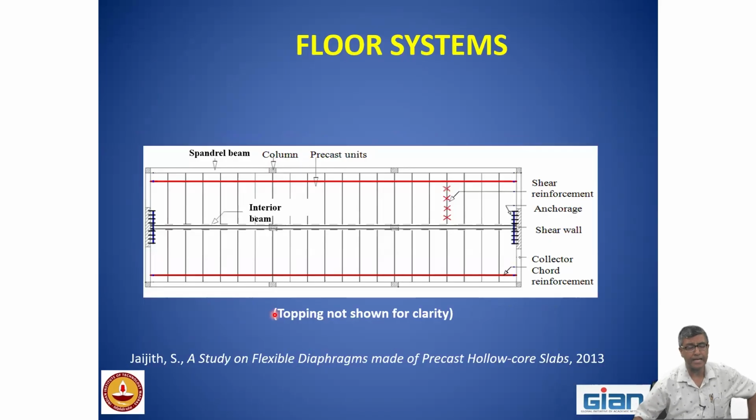Now, this is a schematic sketch of how to design a diaphragm, that we are making the floor jointed, but they have to be integrated to act like a monolithic member to mobilize the vertical lateral load resisting system. Since if the aspect ratio gets large, it tends to bend in plane outwards, and hence they will try to separate out. We need to provide reinforcement at the two edges. Please note, earthquake is a dynamic load which is reversible in nature, and these reinforcements are called the chord reinforcement. Okay.